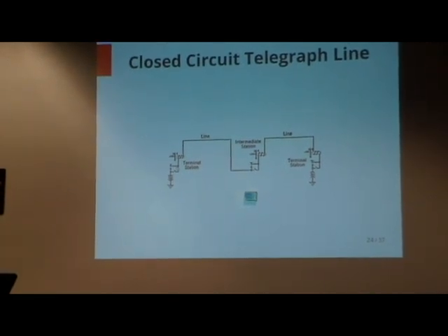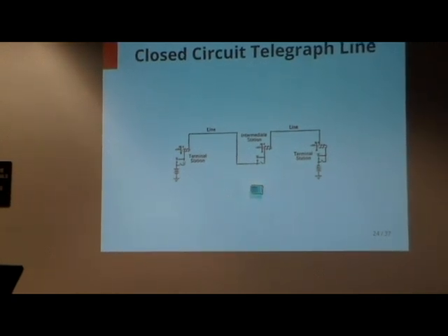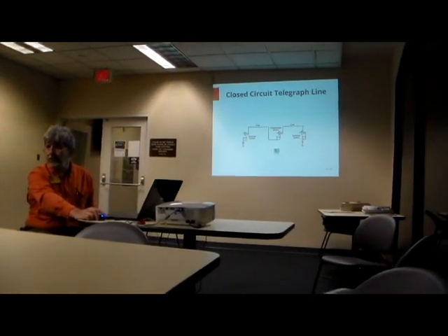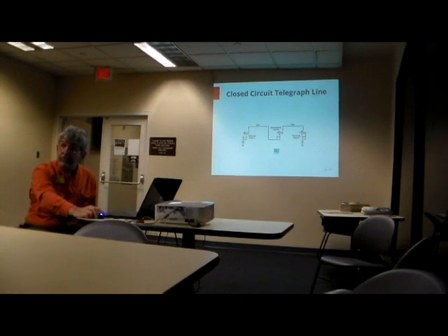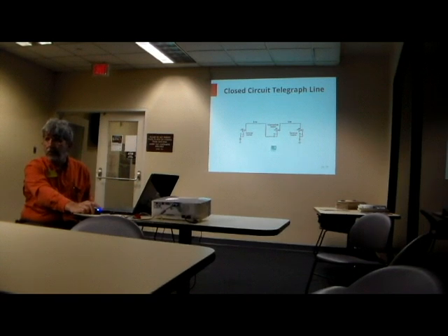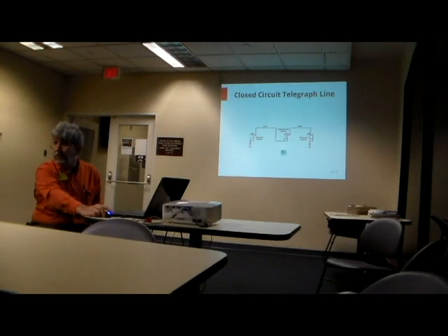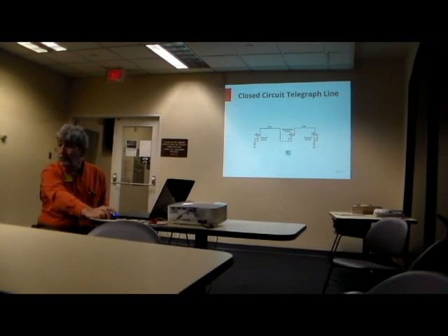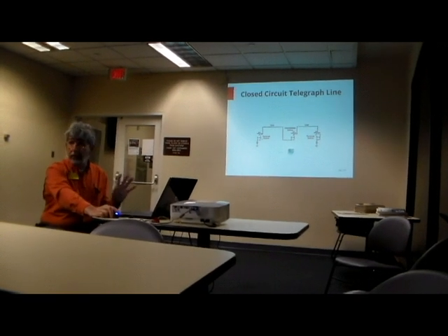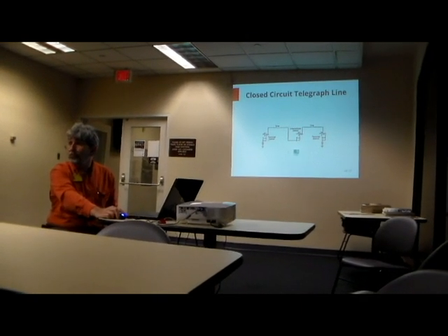The normal condition of the circuit closer on a North American telegraph line is closed unless the circuit is engaged, and then the telegrapher that needs to send opens his closer, sends an attention signal, sends the station signal of the station that's supposed to receive the message, and recloses his closer or her closer so that the other telegrapher can answer and confirm that they're ready to receive. Just leaving his own closer open would cripple the line. In Europe, they did something different that I'm not going to go into. It was a later development. It had its strengths, but it also had some drawbacks, as you'll see when we go over troubleshooting.